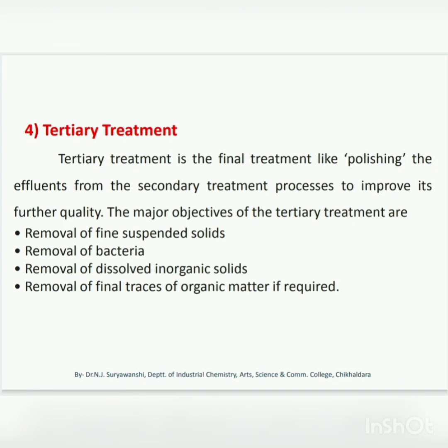Now let's see tertiary water treatment. Tertiary treatment is the final treatment, like polishing the effluents from the secondary treatment processes to improve their quality further. The major objectives of the tertiary treatments are removal of fine suspended solids, removal of bacteria, removal of dissolved inorganic solids, and removal of final traces of organic matter if required.